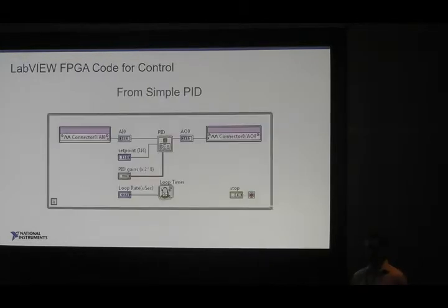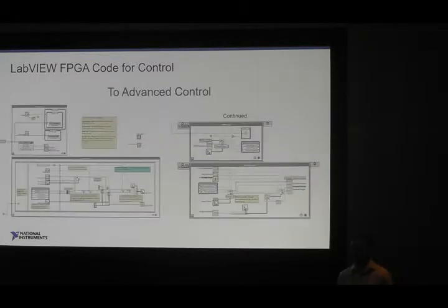Switching over to the FPGA, this group does it pretty well. You can do things from very simple, such as PID here. That looks pretty clean and straightforward, all the way to very advanced options. In this case, I took one of our soft motion examples to do field-oriented control for a brushless servo drive.